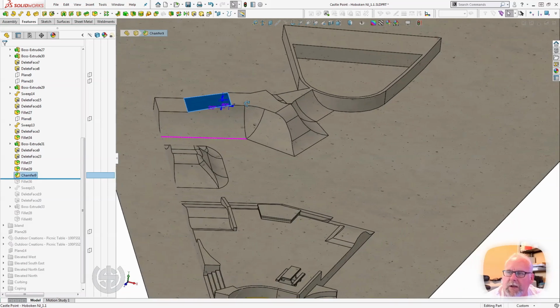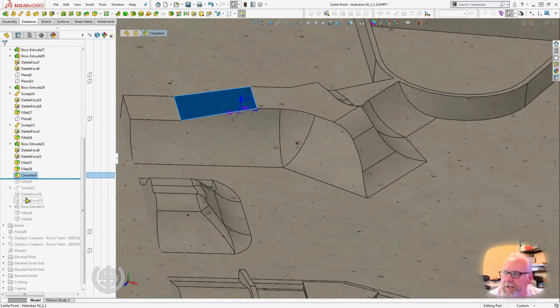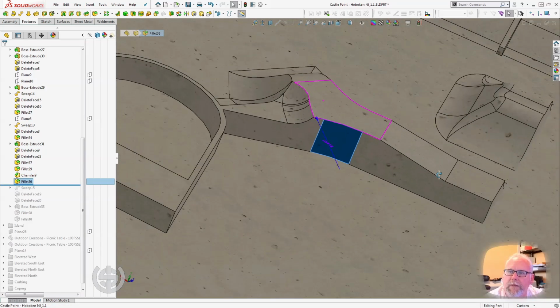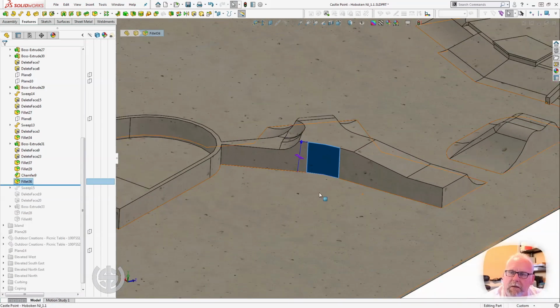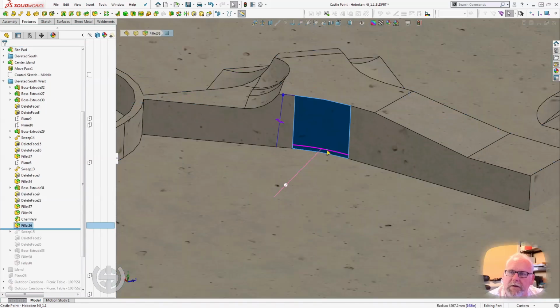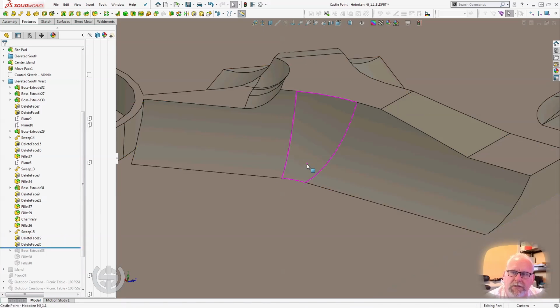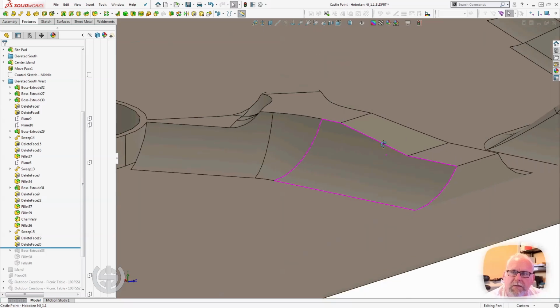This big chamfer here to blend these faces. Probably ease the sharp corners. No, what did I do? Nope. Okay, there's a fillet there. There's going to be a sweep across that face. Then I'm going to delete face the top again. Looks like I had to do it in 2 stages to get it to complete.